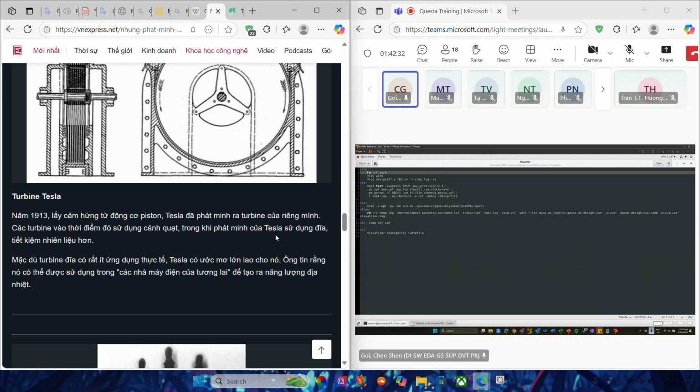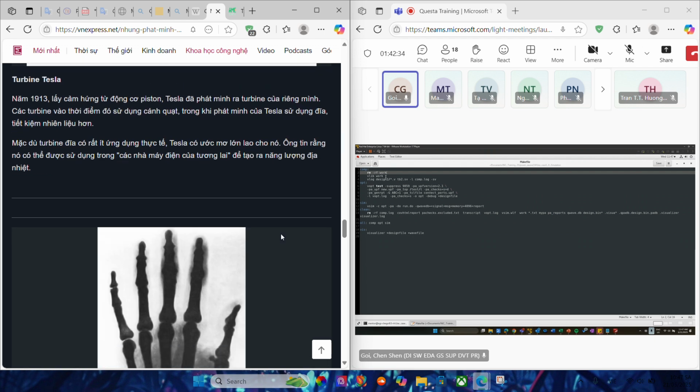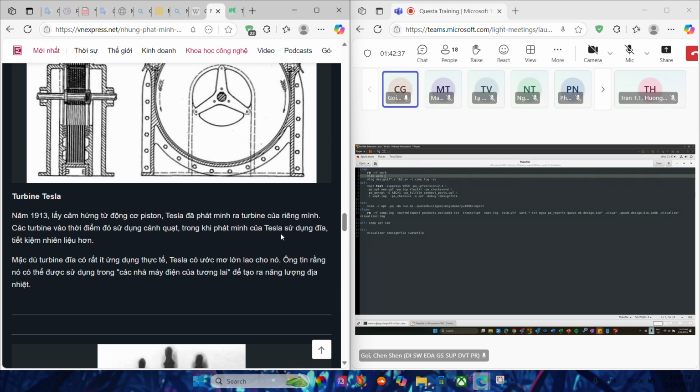So on compile, we just do a clean compile. We remove the work directory, and then we create a work directory, and we just use vlog to compile all of the SystemVerilog and Verilog files. So we have -l here to generate the log file, and also -sv to specify SystemVerilog compilation.